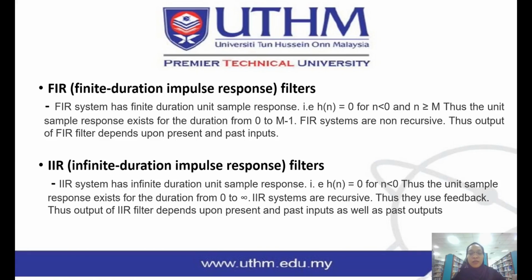The FIR system is non-recursive, meaning the output of the FIR filter depends on the present and past input, while the IIR system has an infinite duration unit sample response, which exists from 0 to infinity. It is recursive and also uses feedback, and the output of the IIR filter depends on the present and past input as well as a part of the output.